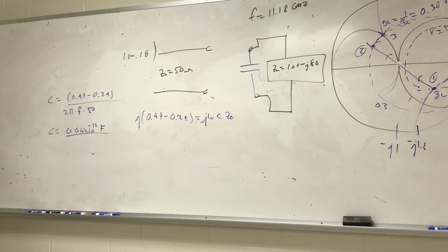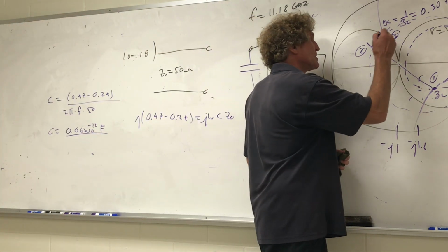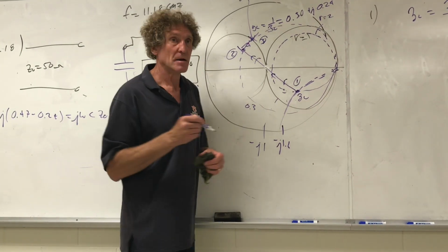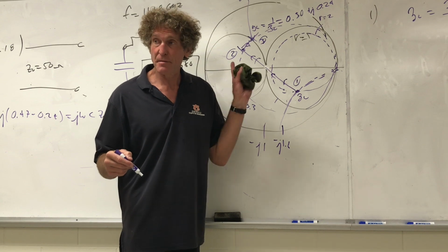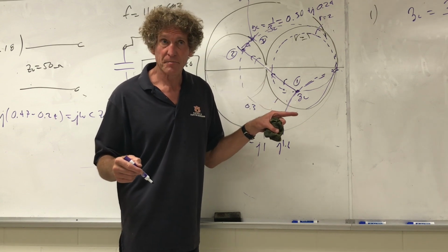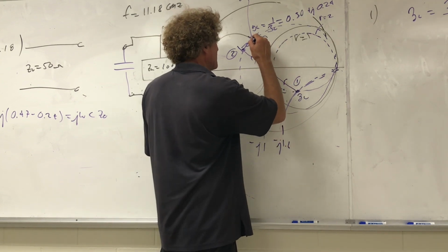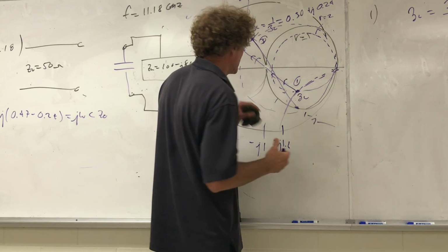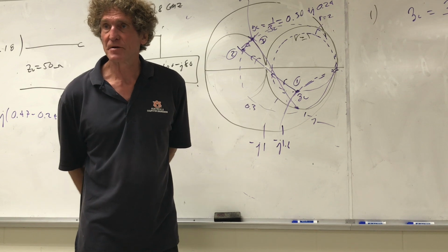Now, how do we get the inductor value? All right, we're here now. That's 0.3, guys. We went from here to here. Now where do we go? Now we go to the impedance domain, right? We're in the admittance, we go to impedance. Do y'all agree, class? Yeah. So now I go back, just take 1 over that, and it better be about 1, 1 minus j something. What's the minus j something? 1.5. Confirm that, someone. Yeah, I got that.